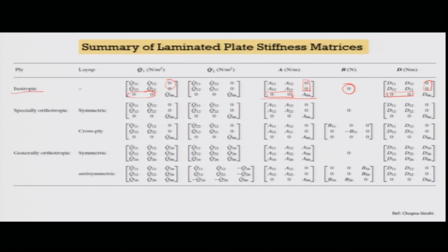Now, we would not be much using an isotropic case, we will come to the spatially orthotropic case, which is like, along the layer we have the conditions of the Q matrix of this type, that these particular things are 0. Okay. So, the elastic constants are not affected along the normal and the shear directions. So, with that kind of conditions, if I consider only a symmetric laminate, okay, what is a symmetric laminate?